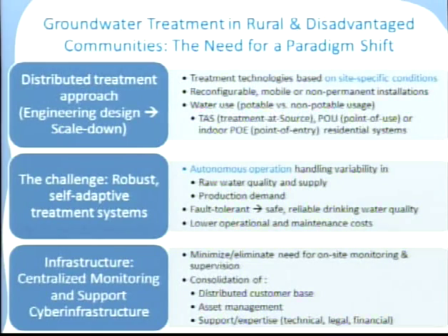But autonomous alone is not enough. The system has to be robust so it doesn't go into a fault. So I used perhaps a fancy term that we use in control, which is basically fault-tolerant operation. So we have what we call fault-tolerant operation and isolation, which means that we know a fault is about to occur, but we also need to know what's happening in the system, which sensor is about to fail, which component, which valve is not operating properly. So we have to have detailed models of the system that allows us to do that.